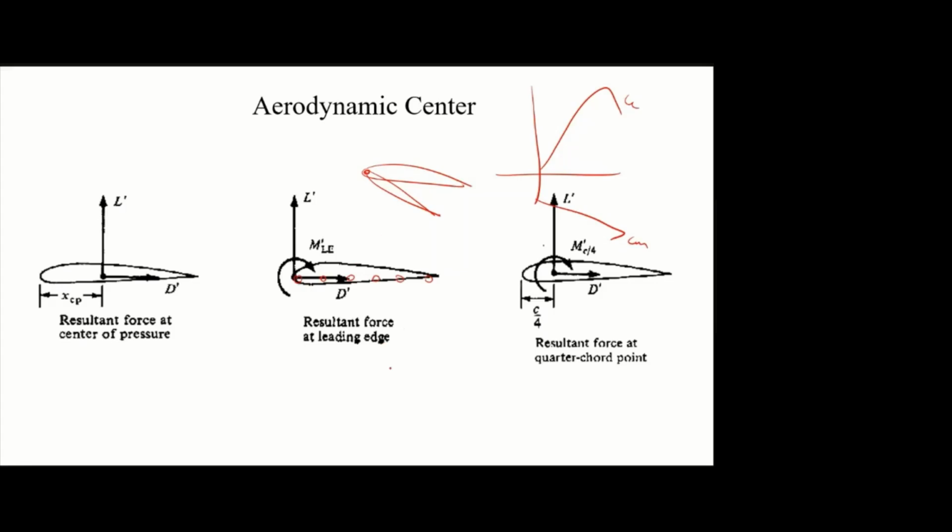Then we are holding at 25% of the aerofoil. Now we are changing the angle, different angles of attack. The CL curve will be the same because it is the same aerofoil, same boundary conditions. Depending upon the holding location, only this moment curve will vary.